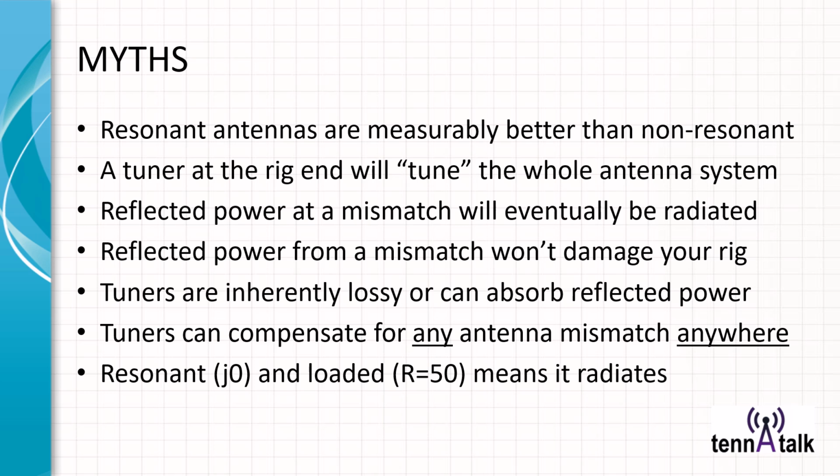Tuners are inherently lossy or can absorb reflected power. In a modern tuner, it's not true. The series resistance of inductors and capacitors are quite good, so the ohmic loss is very, very low. And so tuners are probably 98, 99% efficient, so don't worry about them.